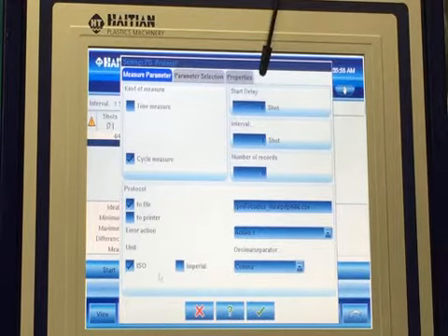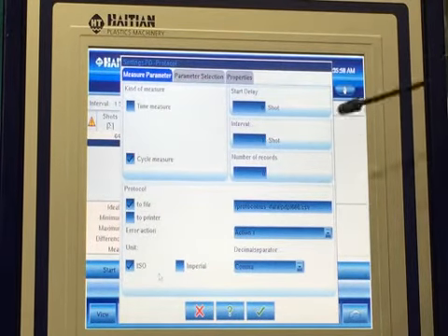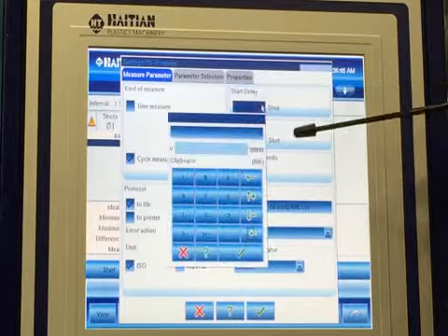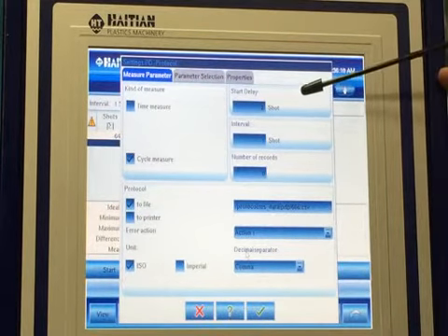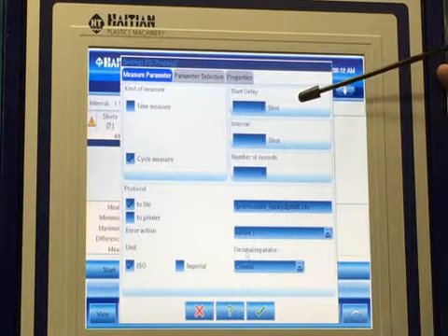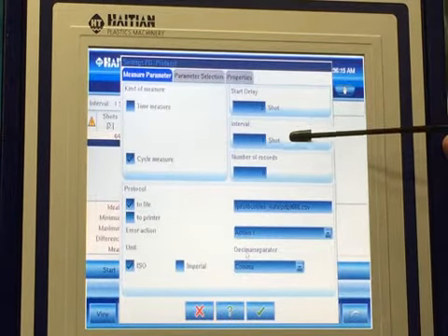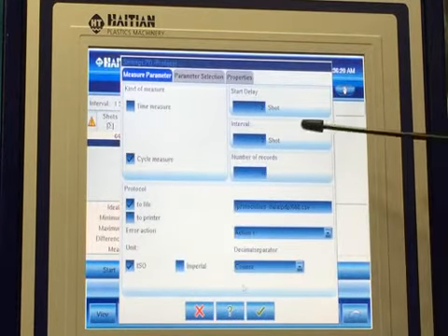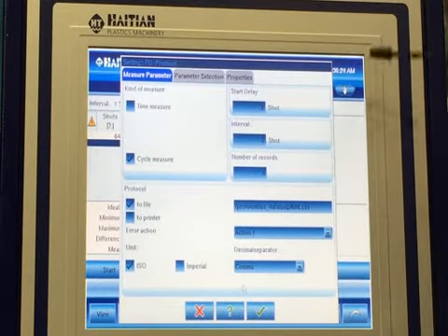If you want to delay the start of it for a number of shots, knowing that you're going to have a rejected part, the first two parts, you could put in 2, and it will not start recording the information for 2 shots. The interval is if you want to record it every shot, or every 2 shots. You can tell it how many records you want to record.